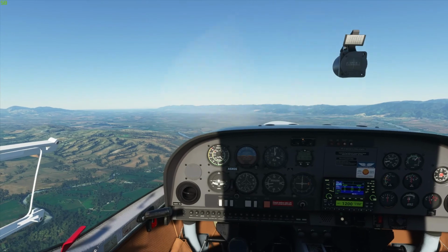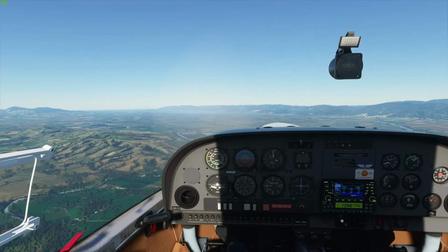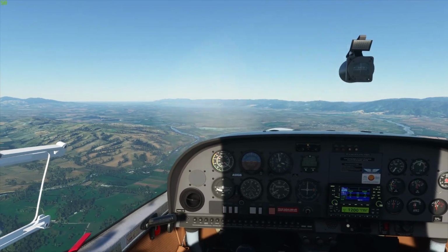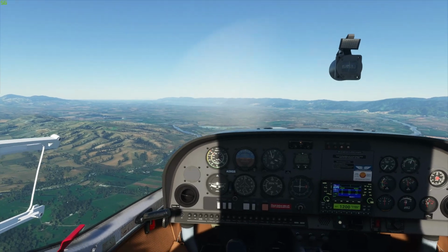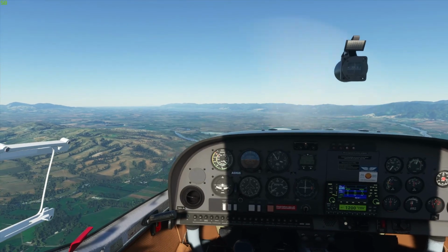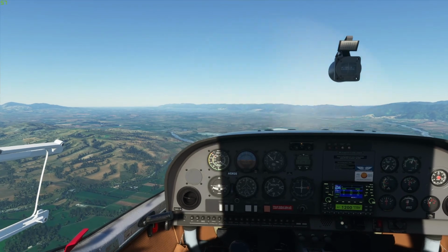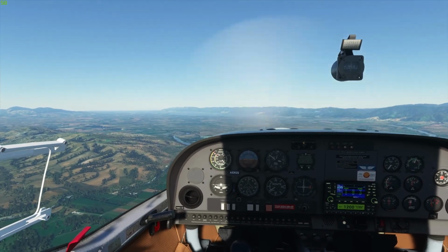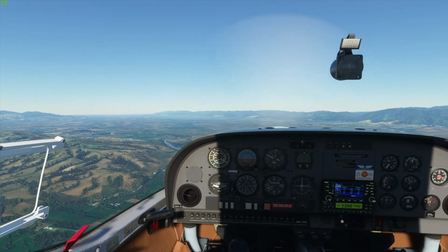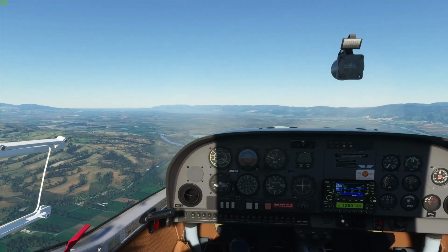And we will just set up a 500 foot per minute rate of descent, and basically just fly it as if we're flying an approach. And we're just looking for the attitude really, because this is so I think 60 knots is probably a good approach speed, so I'll trim for that. So when I say trim for that, that means I'm setting a power setting so that we're descending at 60 knots at about 500 feet a minute. So the first thing I do is adjust the nose attitude for 60 knots, and when I'm flying consistently at 60 knots, then I can modulate the power to set the rate of descent that I want.